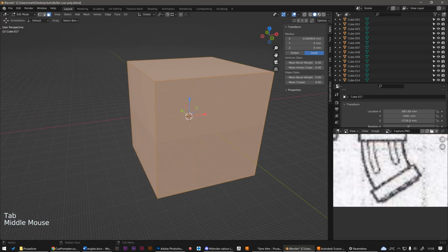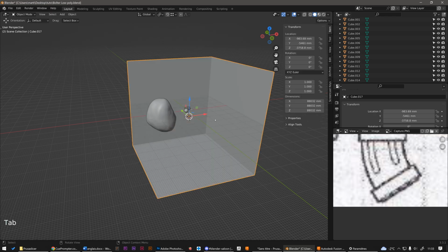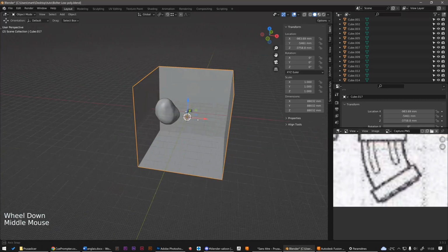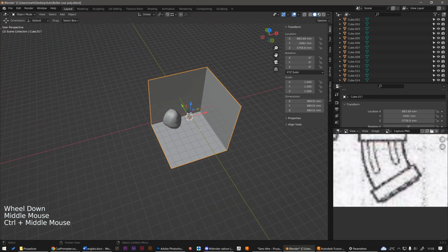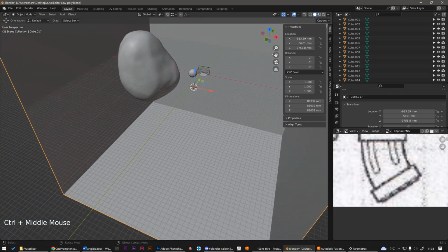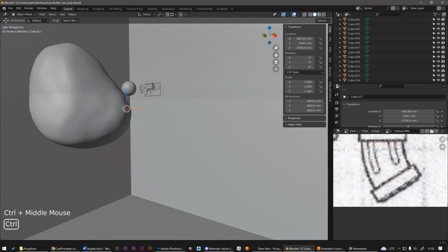Blender has a lot of tools to edit normals that can be found in a menu displayed with the Alt+N shortcut. And in this menu, I can flip normals. So now, the room, or rather the faces of the room, are invisible when I'm facing behind them. But if I stand inside the object, I can see all the faces since they have all their normals facing inward. I hope this isn't too abstract for you.